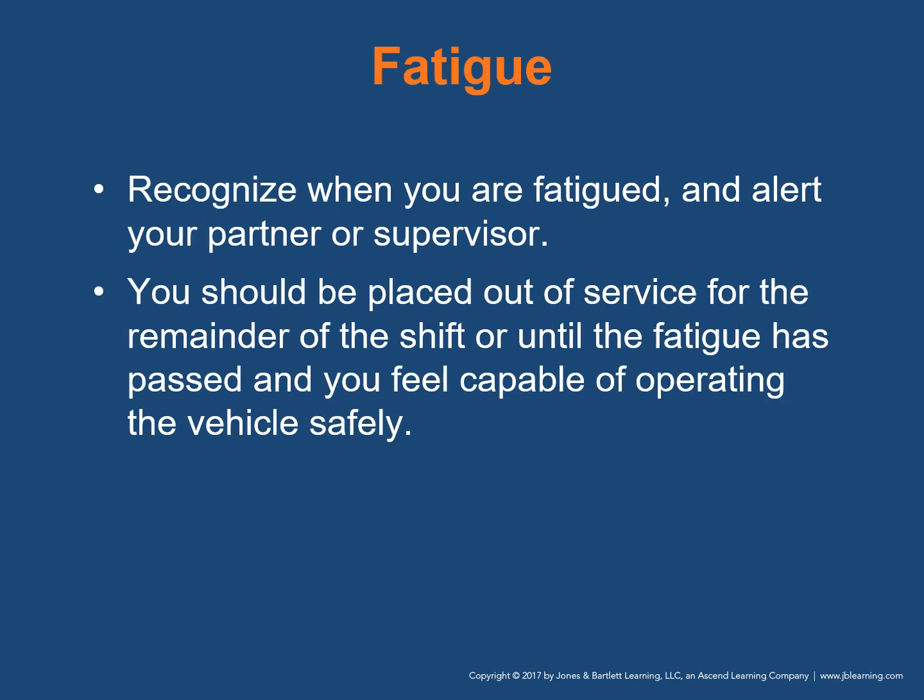Now let's talk about fatigue. Recognize when you're fatigued and alert your partner or supervisor. If you're feeling fatigued, you should be placed out of service for the remainder of the shift or until the fatigue has passed and you feel capable of operating the vehicle safely.